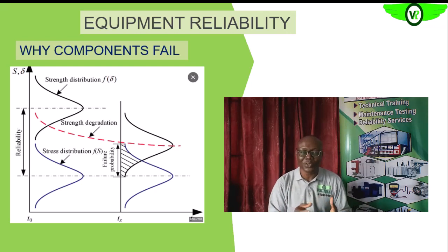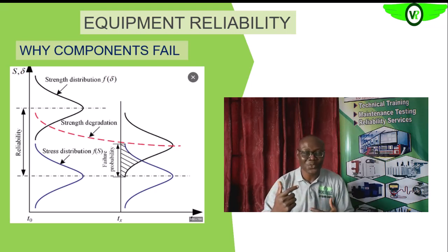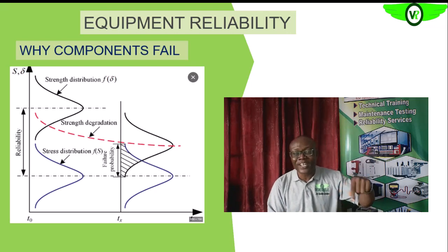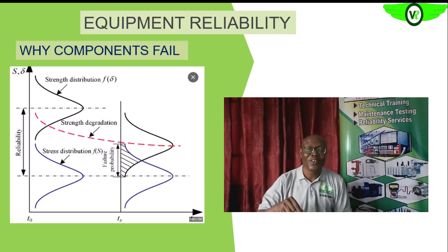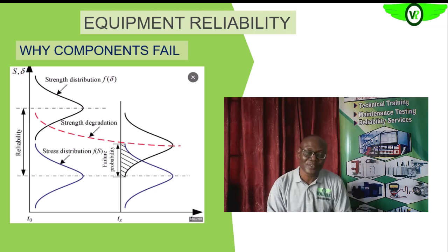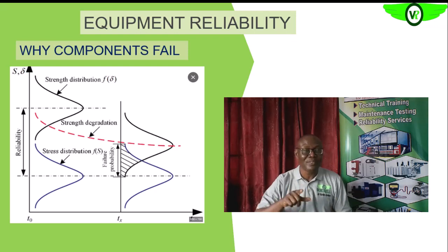But you know that during operations, there are times the stress level will overshoot that 2 psi. And maybe because of maloperations and what have you, or an unreliable operator, we may even have up to 4 or beyond 4 psi in the system. Once that happens, at that moment the component is stressed. Then if the operations are rectified and the pressure comes down, everything will appear to be fine. But know that the equipment has been stressed.